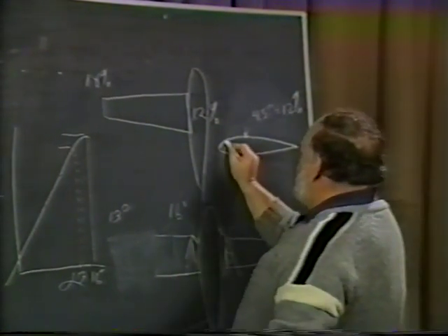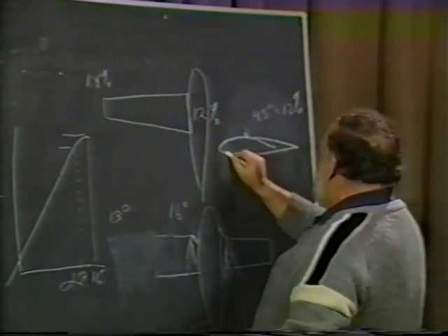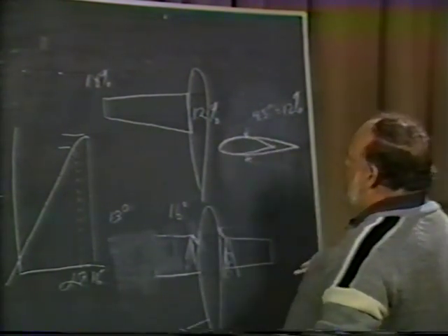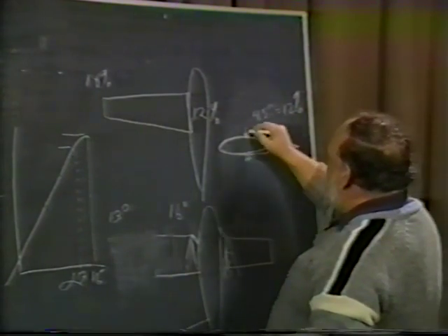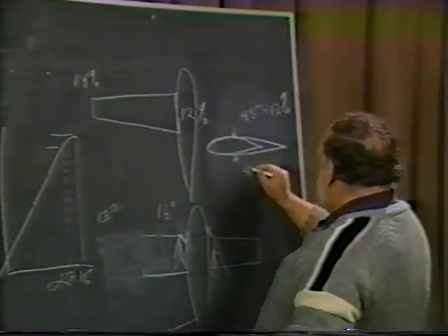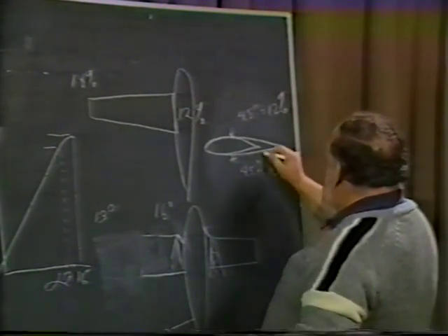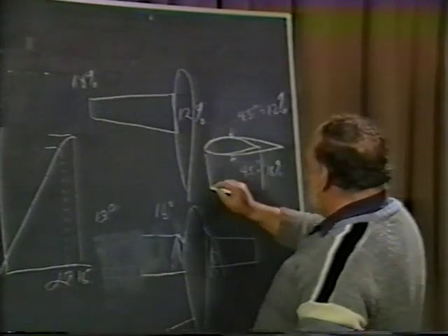We drew the tip airfoil in here with its smaller chord, and it also had a maximum thickness of 4.5 inches. But this 4.5 inches equaled 18% of this shorter chord.